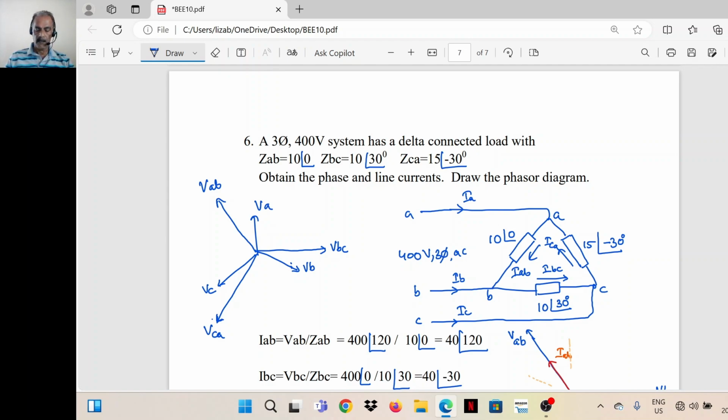Now let's take VA, phase voltage. VA is equal to V phase angle 90. Whatever is the magnitude, at an angle of 90. Assume a positive sequence VB, VC. These are phase voltages. The corresponding line voltages are VAB, this is VA minus VB. This is VB minus VC. VC projected backwards, and the resultant. So this is VBC, VCA. So I'll write the equations for that. This I randomly have chosen.